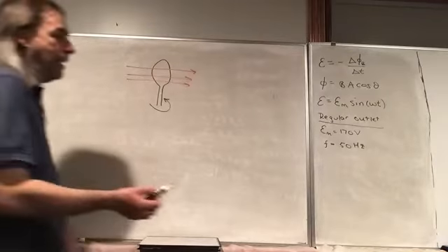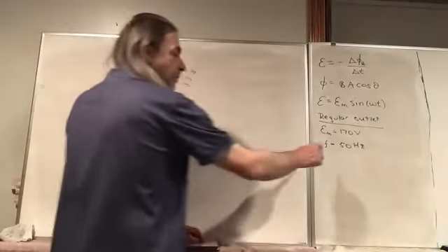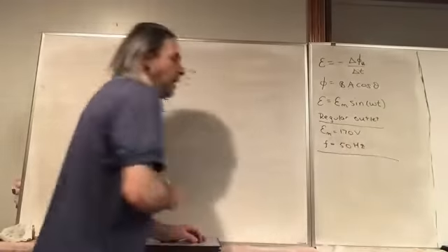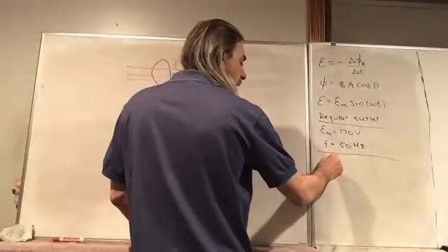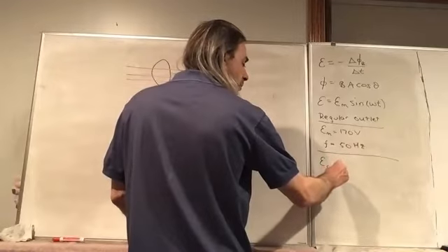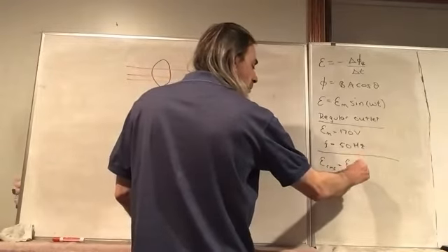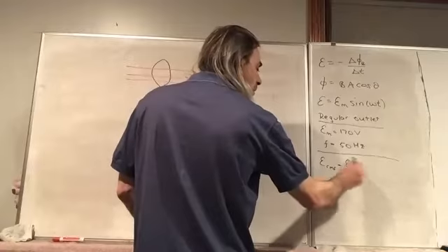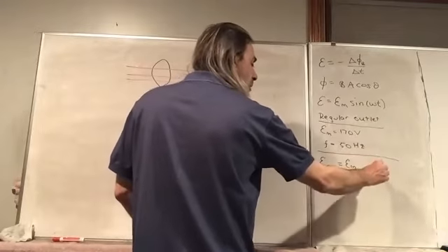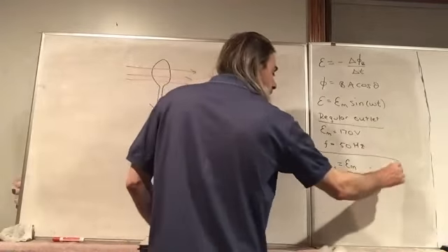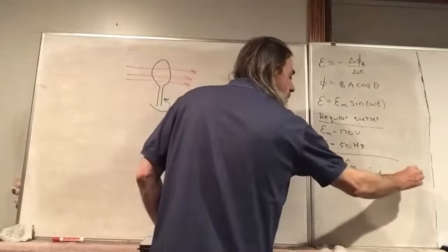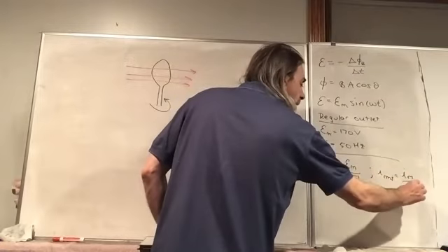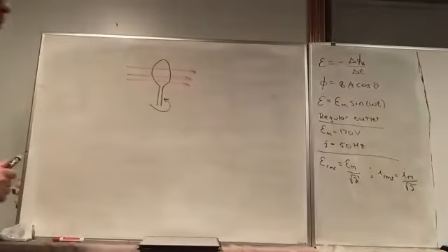So yeah, how the voltage and current peak values and the RMS values are related, they always have that square root of 2. So the RMS voltage would be the peak value over the square root of 2, and the current that we get out of this would be the peak current over the square root of 2.